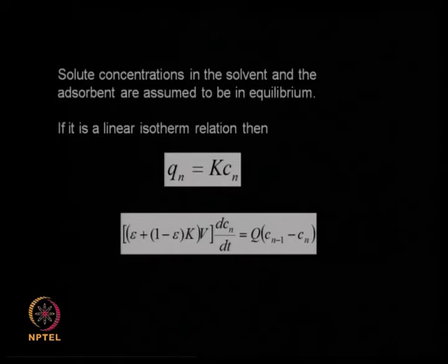So, this is called a differential difference equation, because you are going to have many equations like this. This is the differential part, this is the difference part. So, there are many techniques to solve it. Please note that we had considered a linear isotherm, that is why we are able to combine all these into a single term. If you consider non-linear equations, we cannot solve them analytically, but once you consider a linear isotherm relation, we get a series of differential difference equations, and then it is very simple to solve analytically.